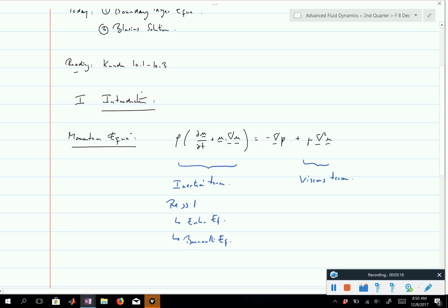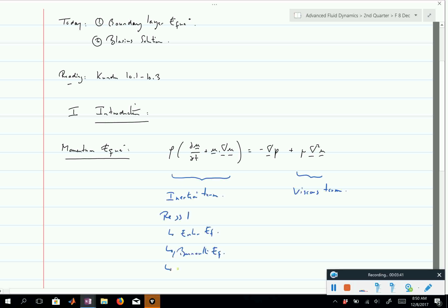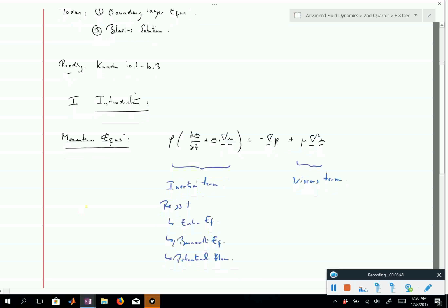So we've been mostly considering this term here, dominant over that term. Right? And remember that the pressure always adapts essentially to what is the leading force. Right? Pressure is just whatever always develops in the fluid if the flow tends to compress or tends to change the volume, say, of that volume of that fluid. So Bernoulli equation, potential flow theory, and so on.